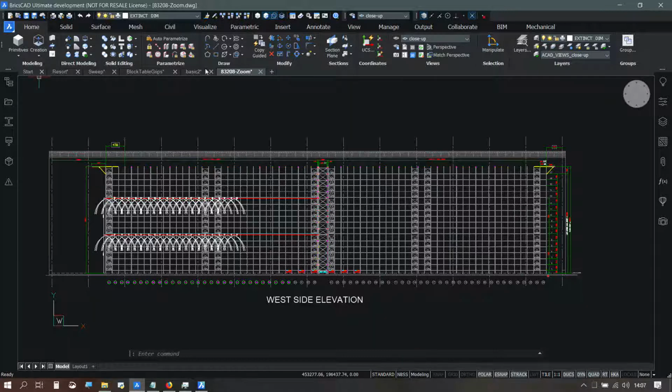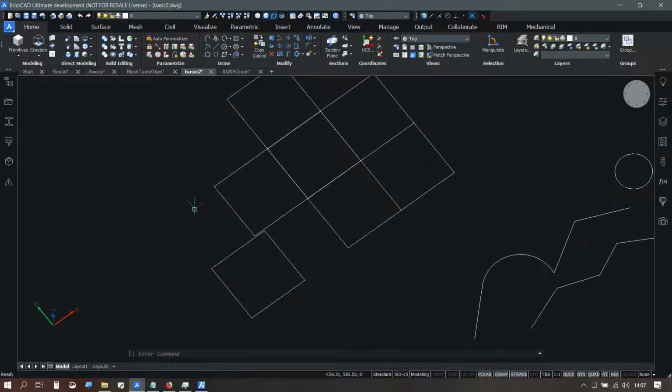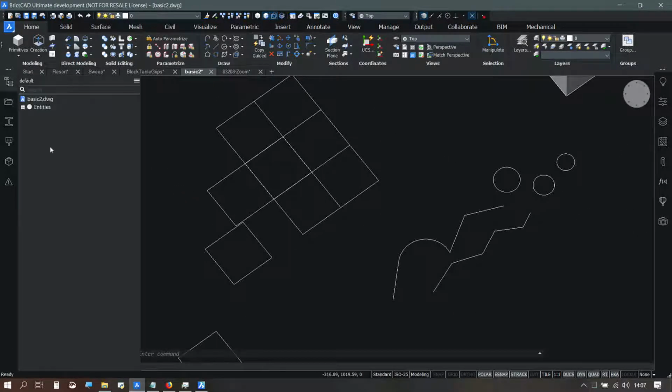Often there are small things. Like in the structure panel, you can select one circle. You can now right click and say hide it. And I select the line and I hide it. And sometimes you have been hiding geometry, but you want to unhide just a few things, not everything again.